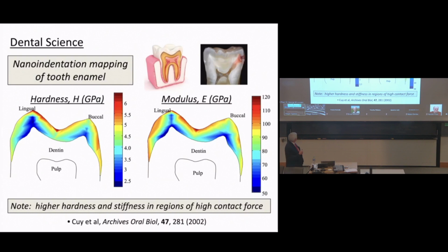On the other hand, if you look down here on the bottom, that stuff down there is not very hard. And in fact, that stuff down there has actually got a smaller modulus. And so it's stretchy, it's stretchier, it's spongier on the bottom. Now, why is that important? Well, that's important because when you bite down on that nut, you put this top surface into compression, but that whole tooth is bending like a beam. And the bottom surface is going into tension.